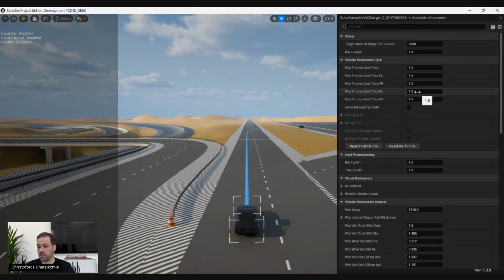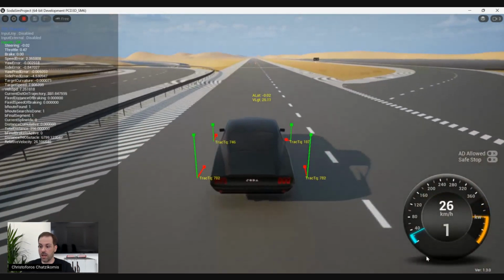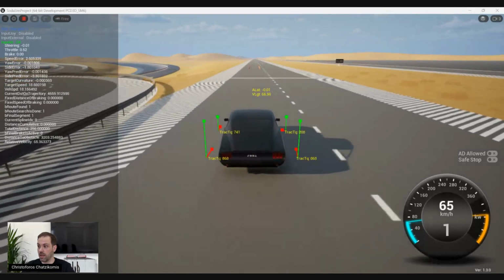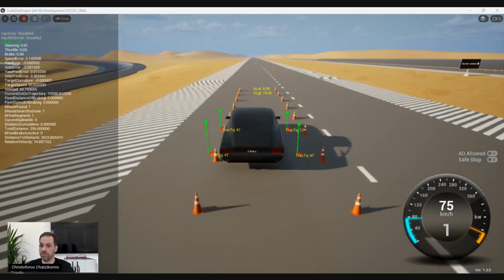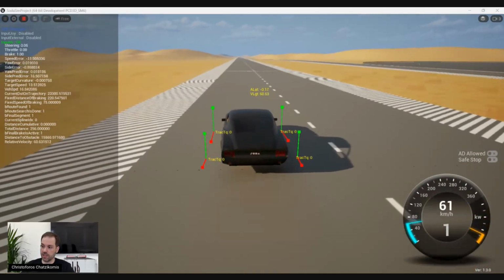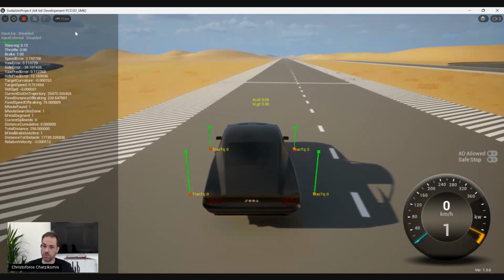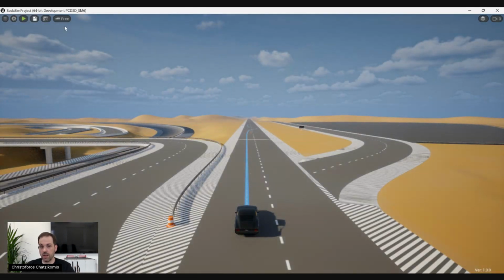start, we can check, we can change something different. So for example, we can change the friction coefficient of the rear tires to simulate what would happen if we would have worn tires. So in this case, I'm expecting that the vehicle would become more oversteering, for example, and that's what we see here. We see that the back end basically almost spins out. So we see basically that what we just changed in the vehicle model changes the behavior